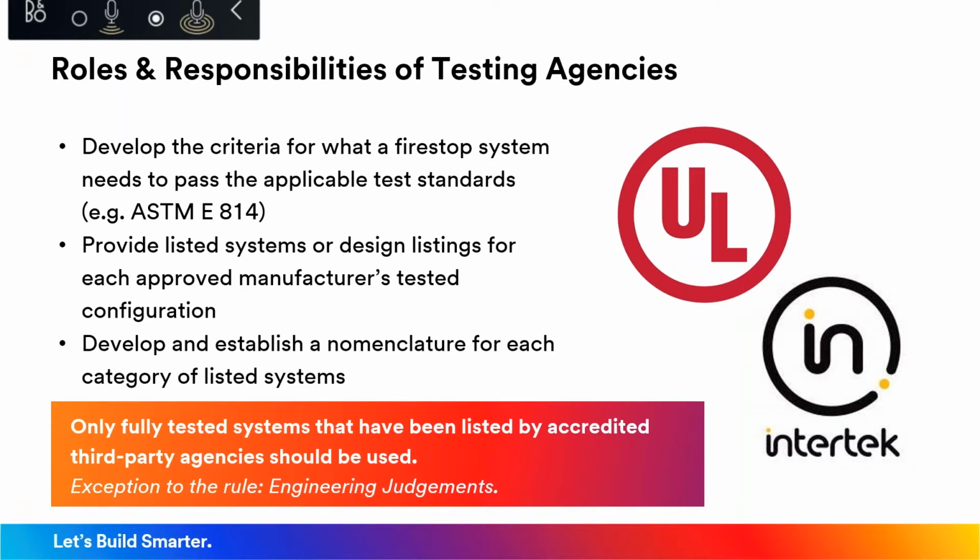Okay, so again, we want to make sure that the product that you've chosen, not just because the packaging says it's 1 hour or 4 hour rated, is installed per a third party listed and tested assembly. And again, that's typically going to default to a UL or Intertek tested assembly.